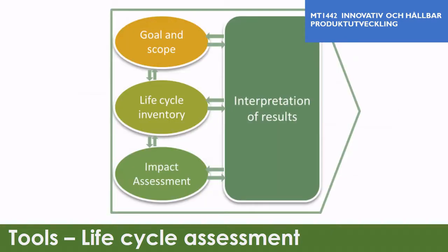So the idea of this tool is that you have to define a goal, like why you want to do a life cycle assessment, and define a scope, like you have to create some boundaries. After that, you will do a life cycle inventory, so you will define what are the inputs and outputs of the process, and after that, you will do an impact assessment. So here you will define what are the impacts of all the process and all the stages of the product development. All the time you are doing an interpretation of results.